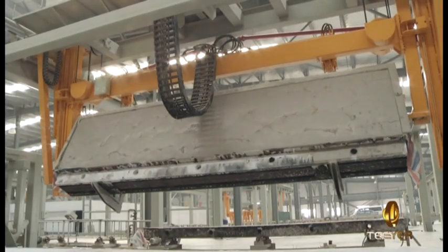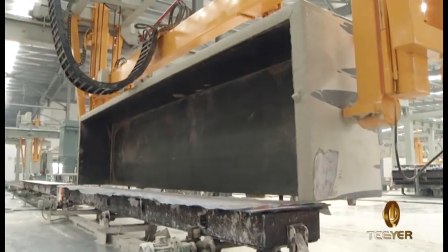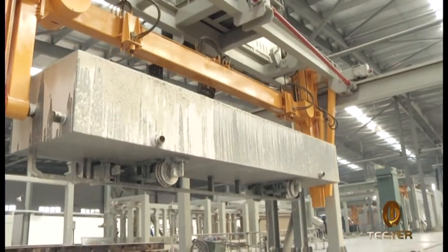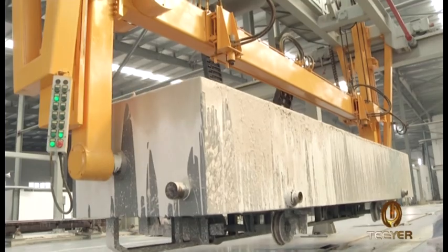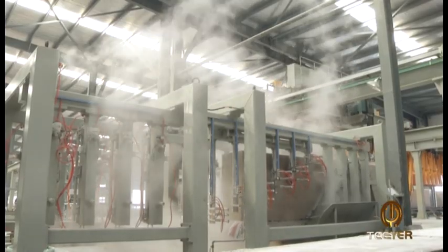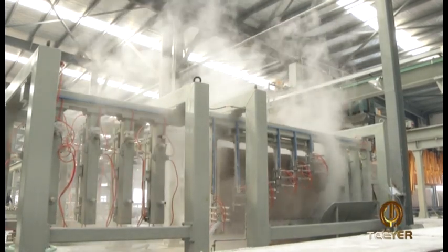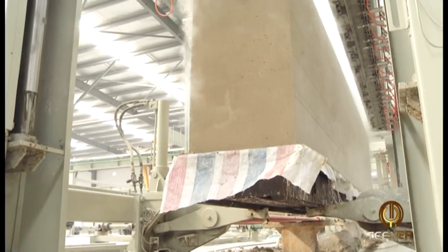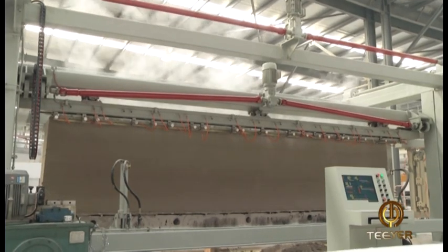The mold is turned over 90 degrees by the tilting hoister and put on the first cutting cart. And then the tilting hoister holds the combined finished empty mold to the returning rail for oiling. The first cutting cart carries the block and passes through the horizontal cutting and groove device to the vertical cutting position. The cart exchange device jacks up the block as well as its side plate for vertical cutting.